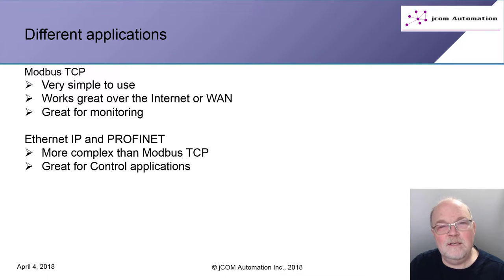To really discuss the details and the differences between these three protocols actually takes me a better part of 2 days to do properly, so this is a rather quick summary. Modbus TCP is very simple to use. It works great over the internet or a wide area network, and it's great for monitoring. But because it uses just the TCP stack, I'm really not big on using Modbus for control.